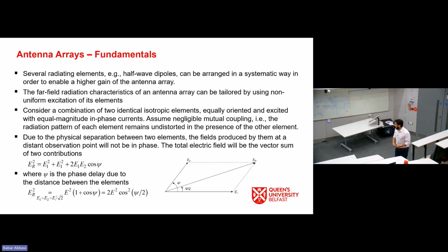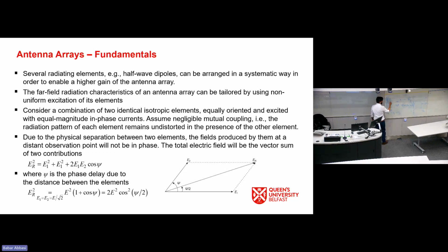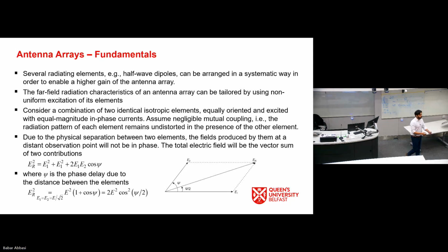Now we are expanding that concept. So now imagine I have a bunch of charges on one dipole producing multiple electric fields and a total resultant electric field E here. Now imagine I have another element here, another antenna here, and it is producing a bunch of electric fields and then my total electric field E. I have E1, I have E2, two electric fields. Then what will happen at this point? My total electric field will be a vector summation of these two. Okay.